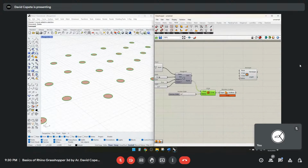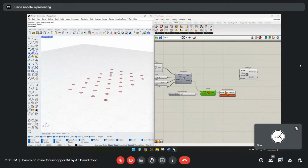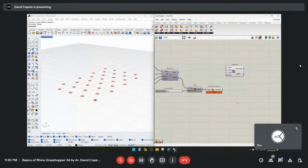So we don't necessarily have to preview this geometry. And now let's take this and we're going to extrude it. So in the same way inside of Rhino, if you want to give this some dimensionality, you have to extrude it. So we'll double click, extrude command. Now there are different extrusions. There's to point, linear, or along. So we'll extrude these surfaces.